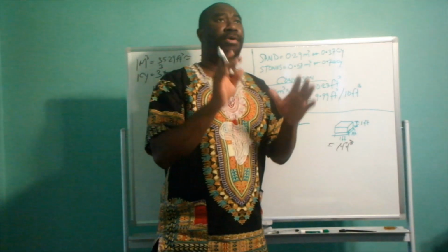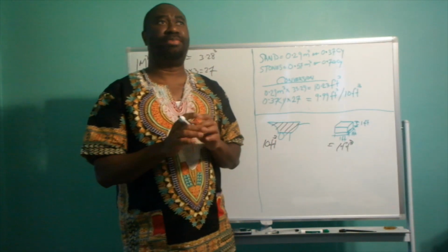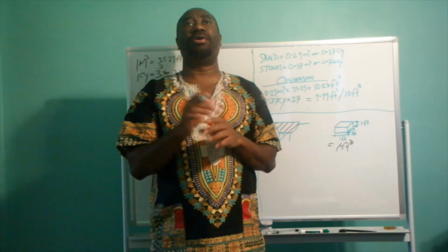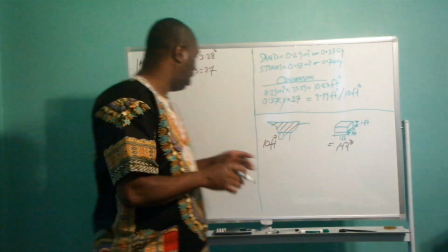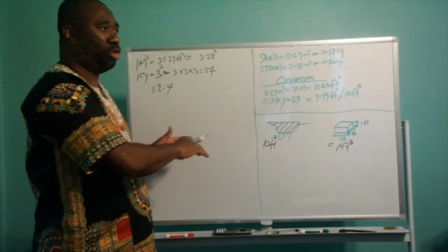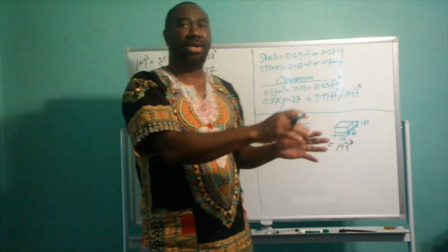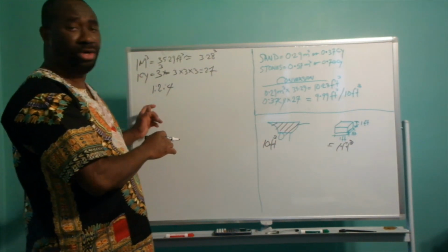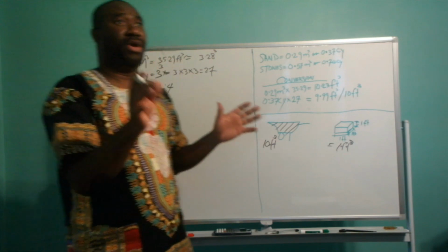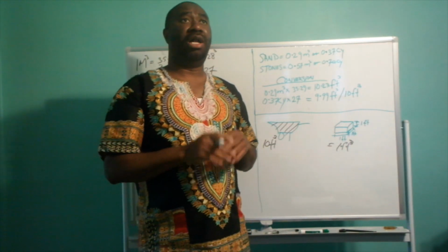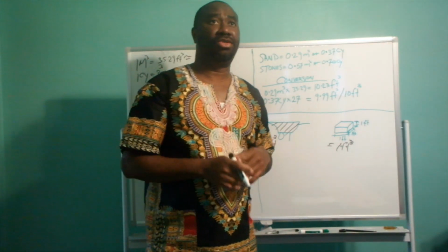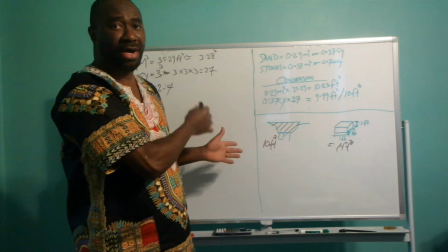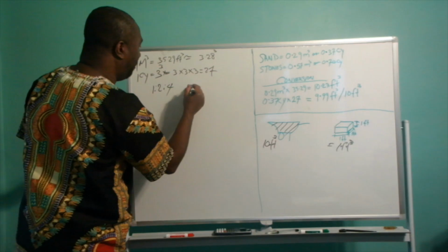If you are the person responsible for running your site, all I'm saying is do not come up with an arbitrary number of sand and tell your labor to just run on that amount of sand without doing the necessary factoring of your ratio. So let's say for argument's sake, you told your labor on site to run on 7 barrels of sand, without factoring the mix. So 7 barrels of sand.